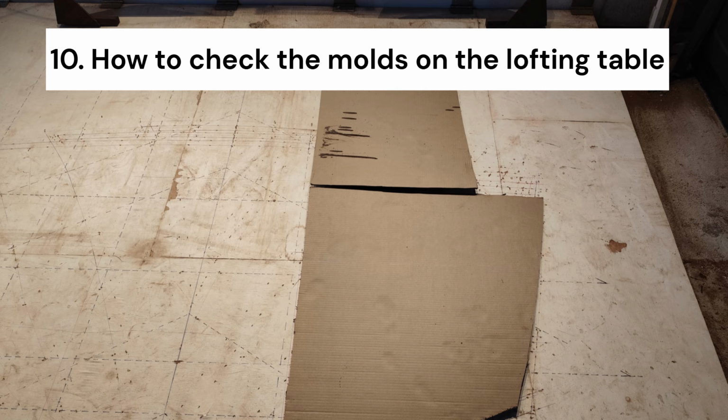You also loft all other needed pieces like reinforcement frames, bulkheads, bow, keel, and transom. Here are shown our molds for bulkheads on Station 7. Due to space limitations in the latter phase, we had to make it in 2 parts.